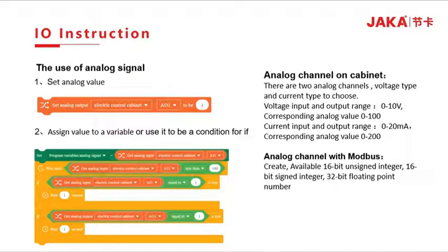The use of analog signal function is as previous. You can change on the drop-down list if we use a tool end or cabinet plug according to where our tool is set. Then you can choose which AO number you want to set, and finally you can set the value you want for the operation. On the lower section you can observe the main operations you can create with the judgment instructions.